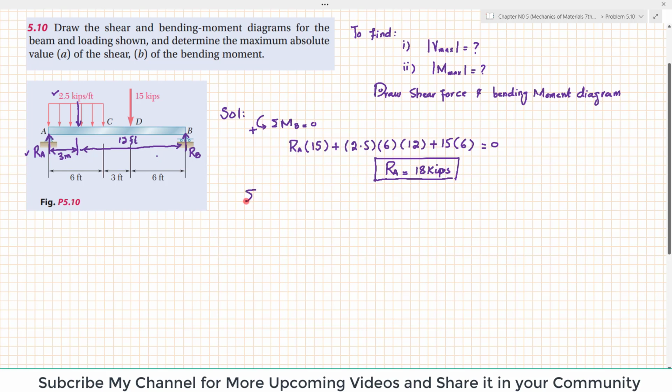Now we will find the reaction force at point B. For that, I apply the sum of all moments about point A equal to 0, taking counterclockwise moment as positive. You can also apply the other condition, that the sum of all forces in the y direction must be equal to 0. Both will give you the same answer, but here I am applying this condition. So moment about point A. The first force producing moment about point A is RB. So RB, and the perpendicular distance is obviously 15. Clear? Because you can see 6 plus 3 is 9, plus 6 is 15.